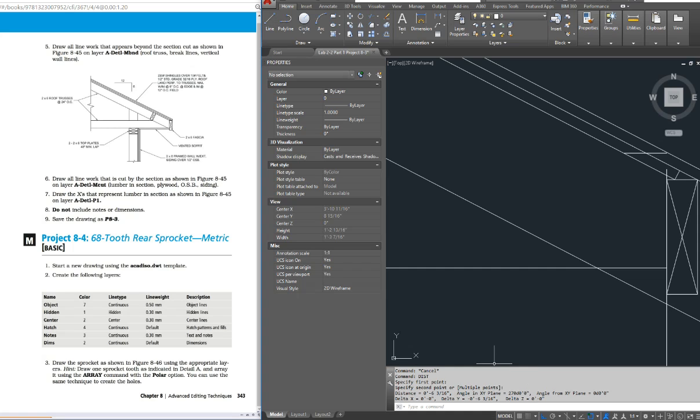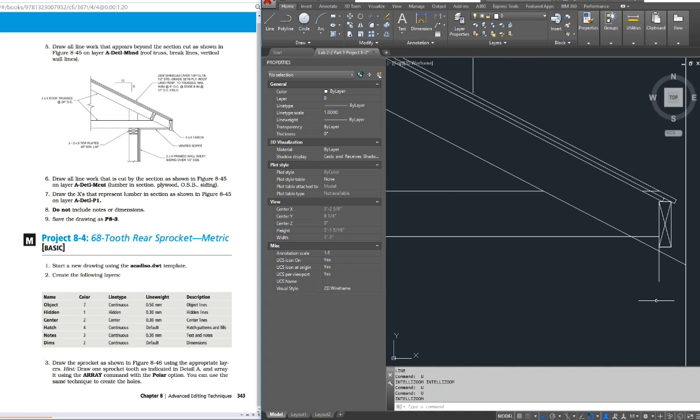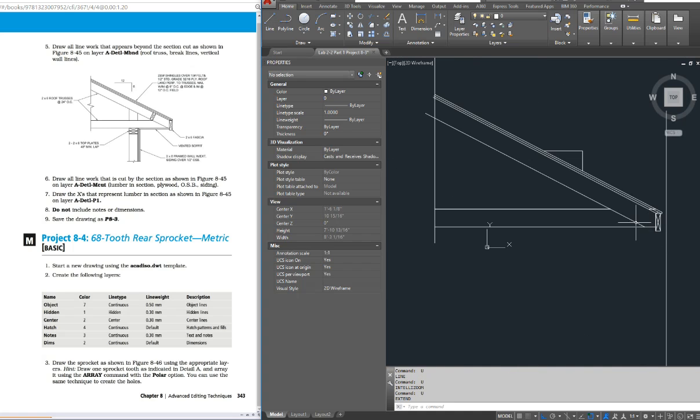But I know that that 2x6 is only 5.5 inches. Now when they cut it on an angle, it will get a little bit longer, but it's not working out here. So I'm going to just trim it so that it's like that. And they'll nail that right on there.